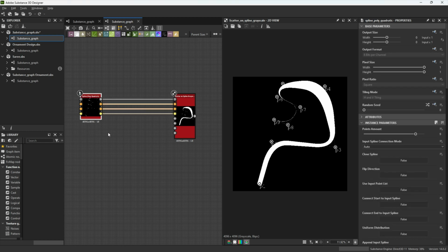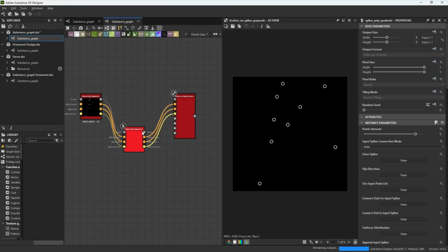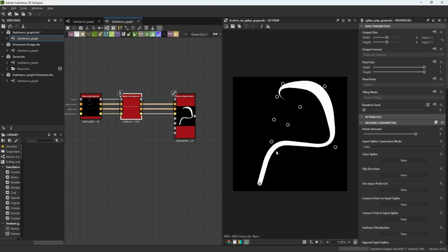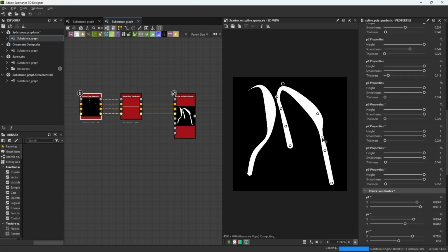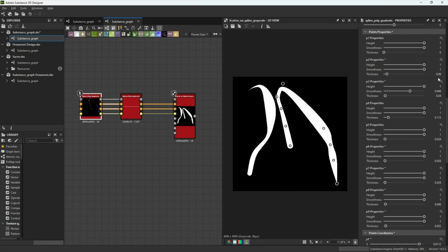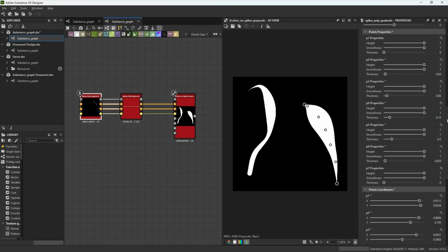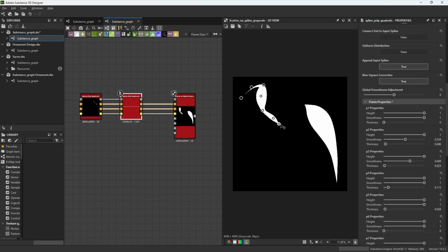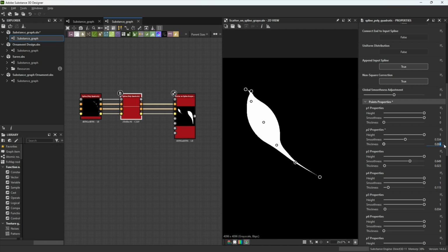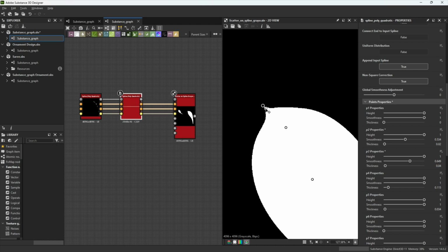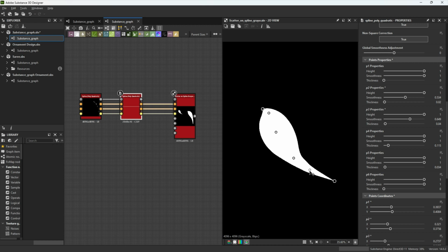If you want 2 different shapes, simply duplicate the spline node and reattach it between the original spline and scatter on spline nodes. Now, you can move the points of the duplicated spline node and the pattern will appear dynamically. Try experimenting with different shapes to introduce variety into your design. You can add multiple shapes to achieve more complex results by layering them strategically and fine-tuning their alignment. This allows for the creation of intricate, visually engaging patterns that can be easily adjusted at any stage of the process. This is particularly useful for adding details and layering elements within the ornament pattern.